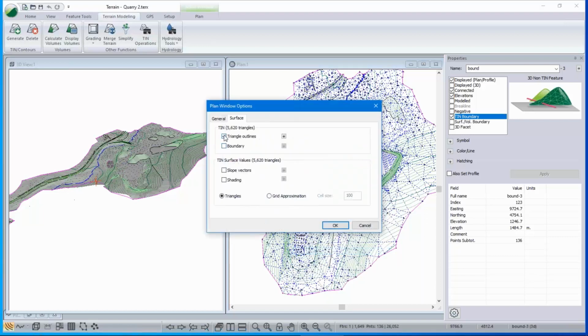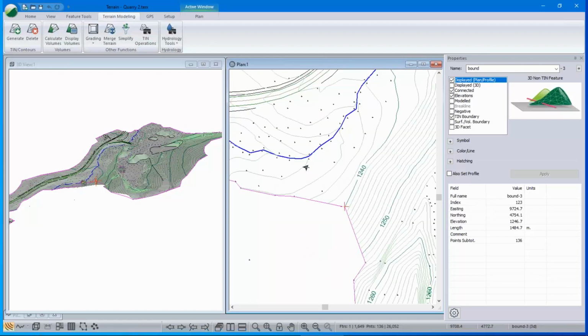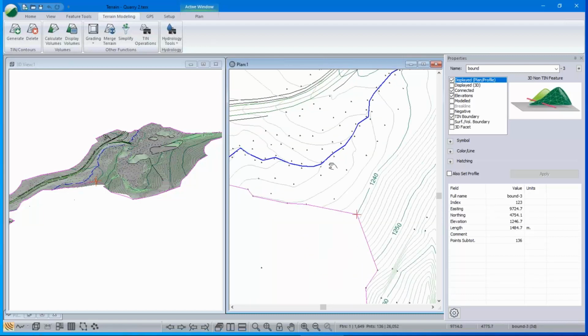Now this model is pretty much ready for our next step, but I wanted to illustrate how you can extend a model. Often a customer comes to us and says, my model's too small, I can't go out in the field and resurvey, how do I make it a little bit bigger? Well, probably the simplest way is just to extend a contour, and the contours, as I mentioned, are not actually part of the model. So here's how you do that.